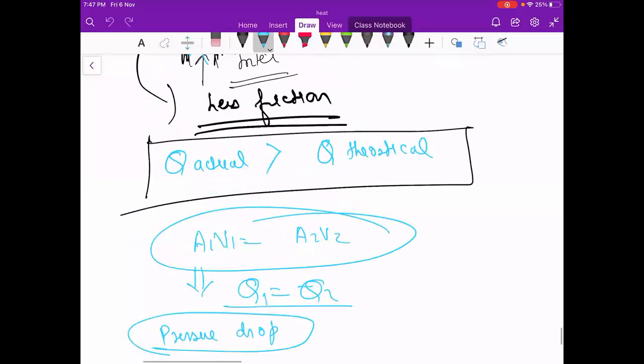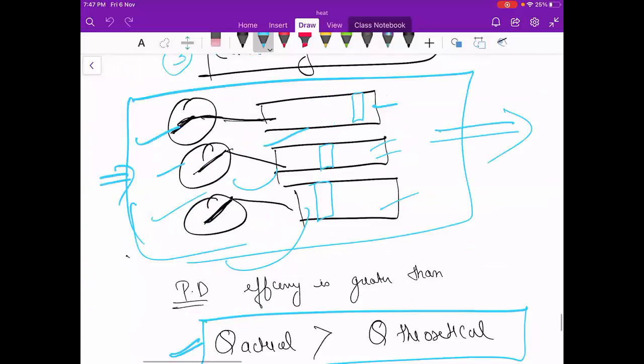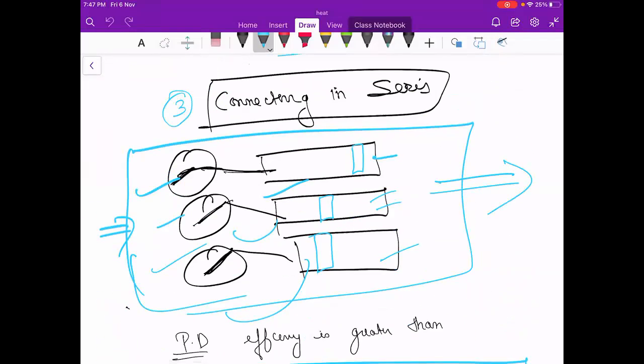Series. What does this mean? This is reciprocating pumps in series. So what will happen? See here, the position of each and every piston is different. So when the fluid is moving from here and coming back, it will be in this position, so it will be giving the flow. Alternately, we have to adjust the angle such that ultimately the fluctuation will be reduced.